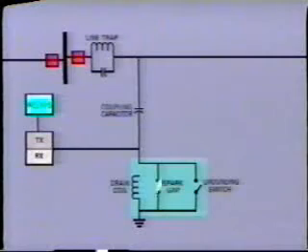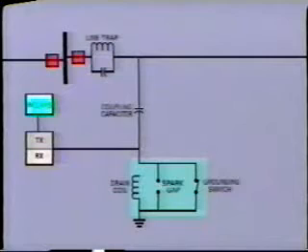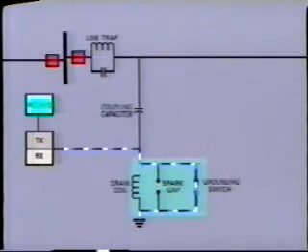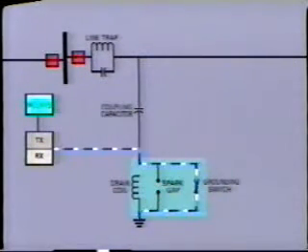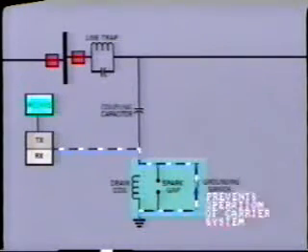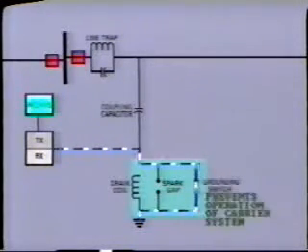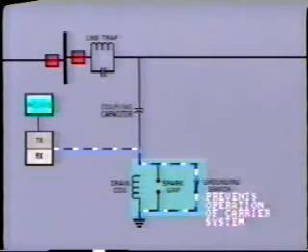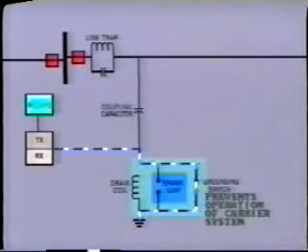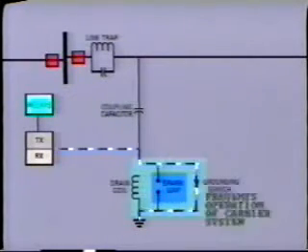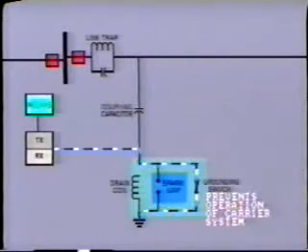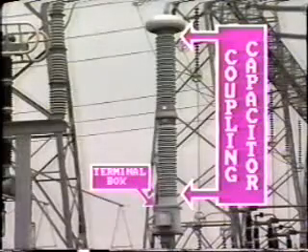At this point, the maintenance staff will have to hot stick the grounding switch closed and replace the drain coil and perhaps the gap. The carrier grounding switch connects the signal directly to ground and effectively prevents operation of the carrier system. This could also occur inadvertently due to protective gap failure, such as foreign material bridging the gap. Regular inspection of the carrier accessories is necessary.